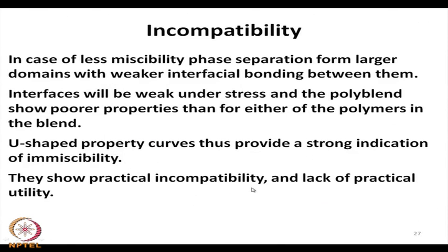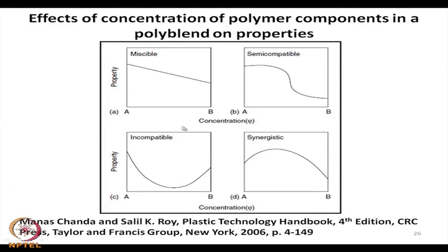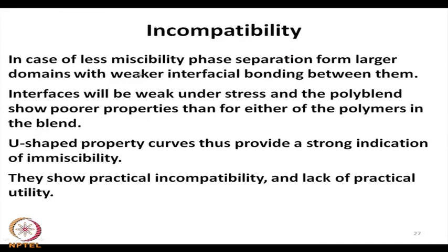Now, in the case of incompatibility, the third component of the curve, here with less miscibility, phase separation forms larger domains with weaker interfacial bonding between them.